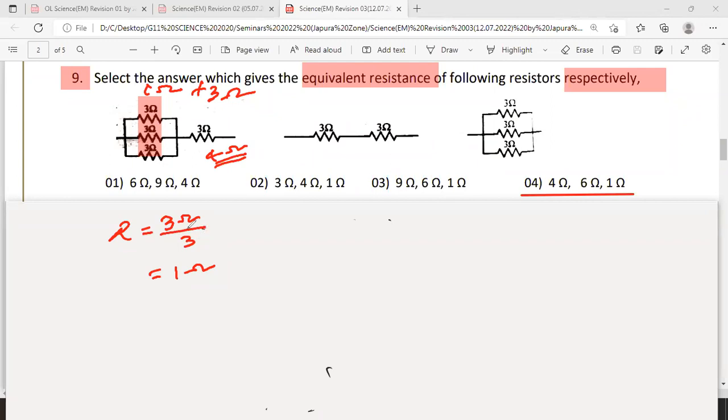What are the two conditions? All the resistances the same value, and they are parallel. Same resistance, parallel. What is the short method? Value of one resistor over the number of resistors. Right. So that's how you get 4 ohms for the first circuit.